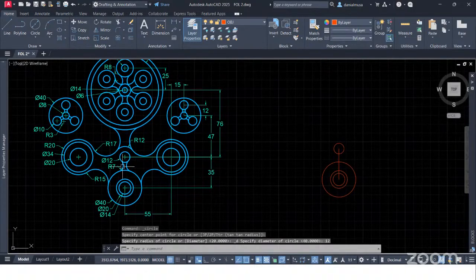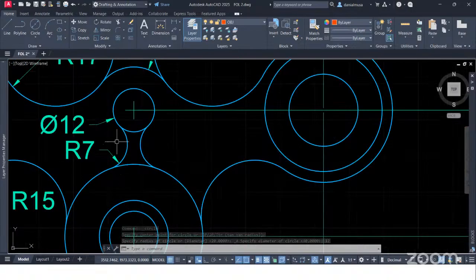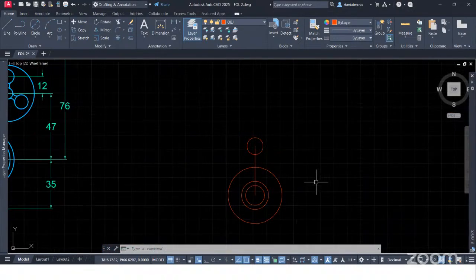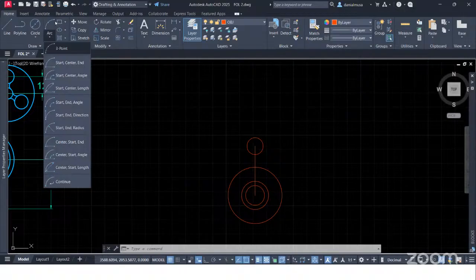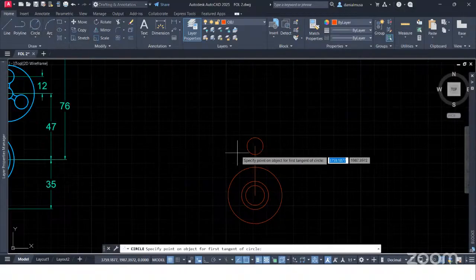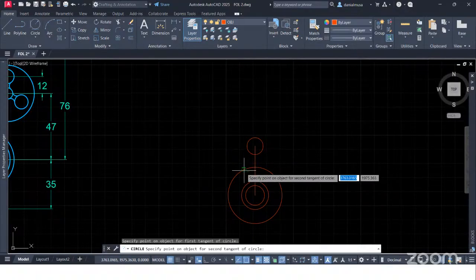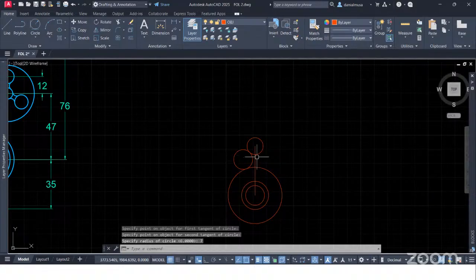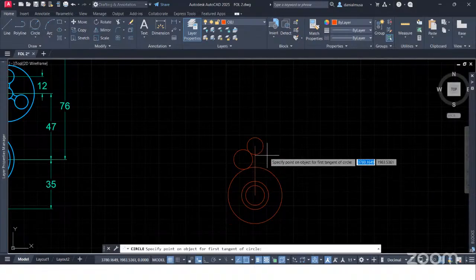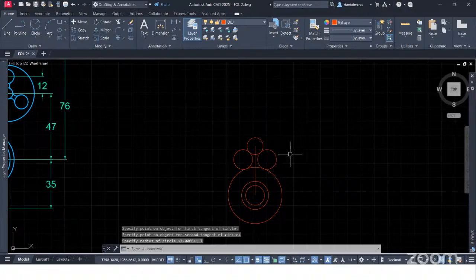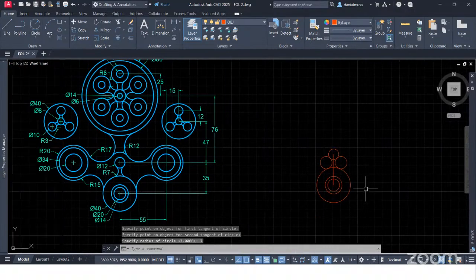Alright, so here it has an arc, with radius 7. Normally you can use the arc tool here, but for me I will use the circle with radius here. Click here and insert 7. Enter and click it again. 7. Alright, so we've removed some parts.